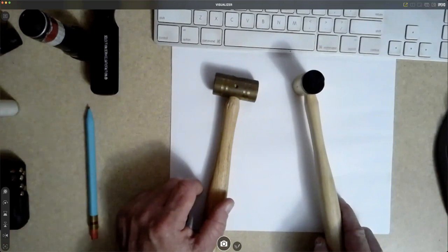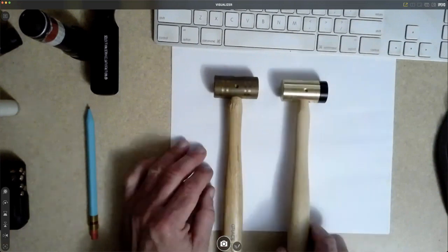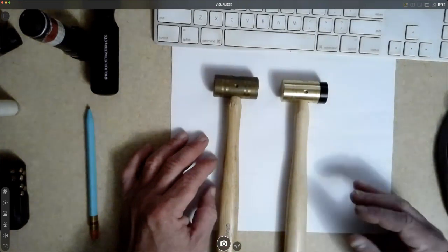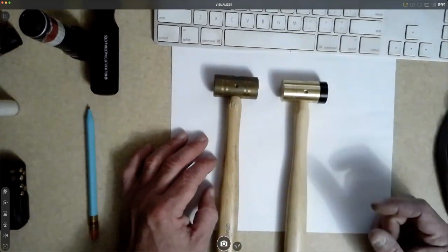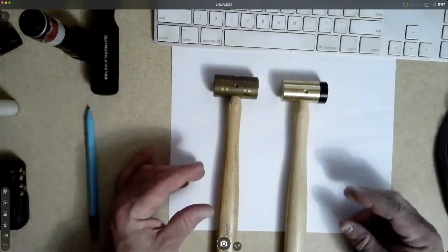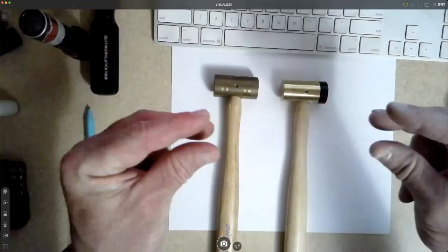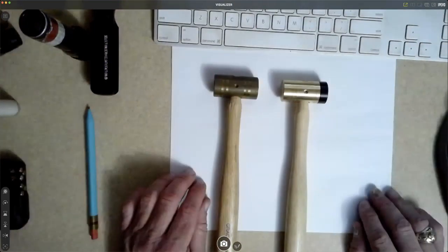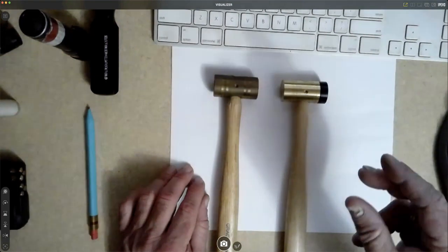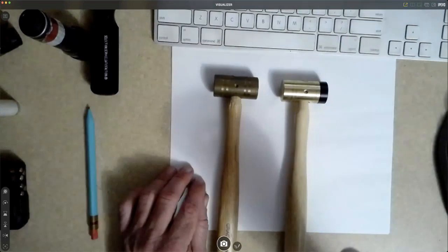The two hammers that I've found most useful on the steel side are the small ball peen hammer that you can get at Lowe's, and the tack driver, the one that's more rectangular and thin. I like those because it's a finer head, so I can be a little bit more intentional in what I'm hitting.